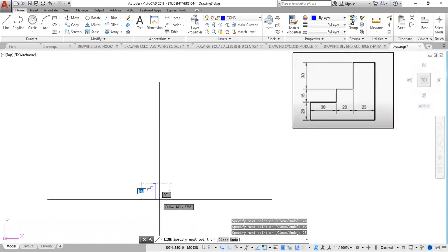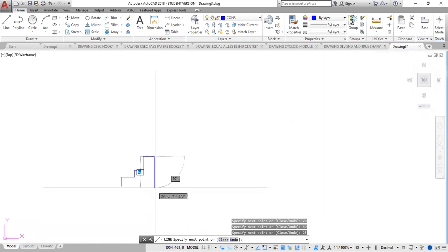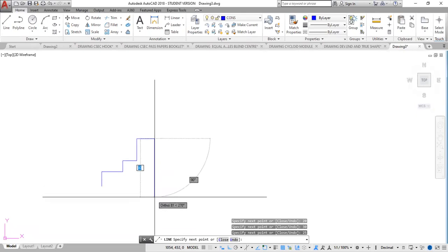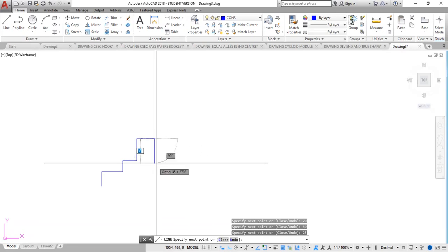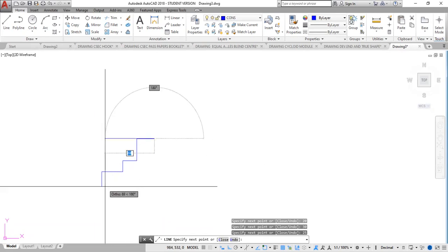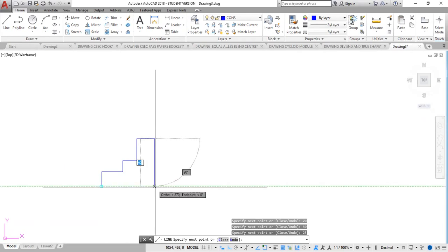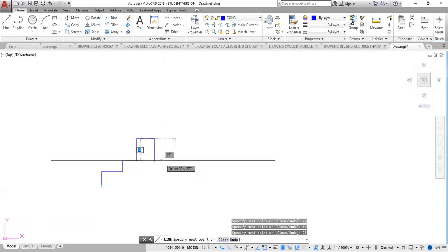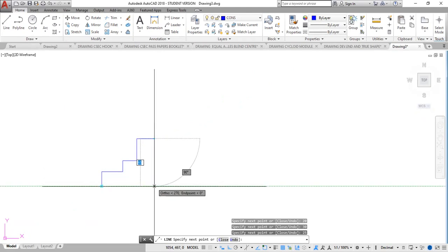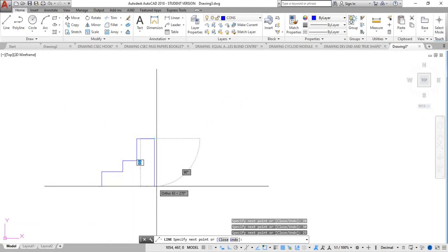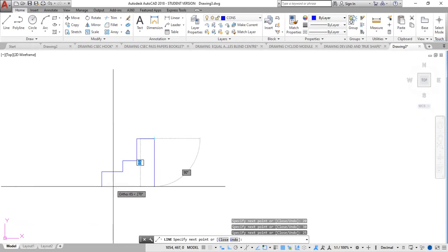The height of this is now 45 plus 20, so 65. We could use a command called object snap tracking. We're going to bring this down. Then we bring this across to this point. We don't click, do not click, then move across. You realize that it formed? Yes. So again, we go down like this. Then we come across here and it automatically snaps there at that point.